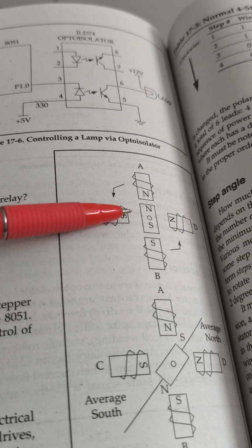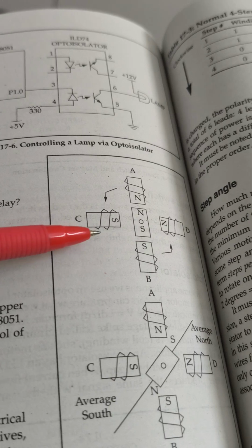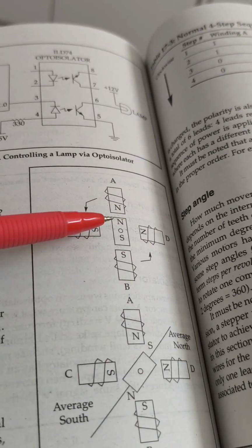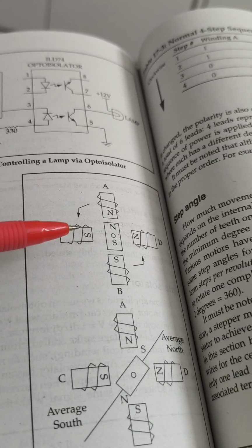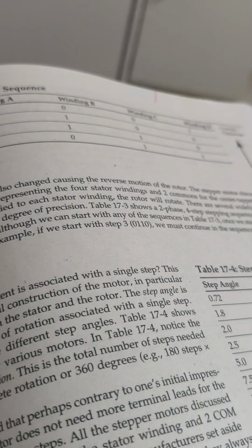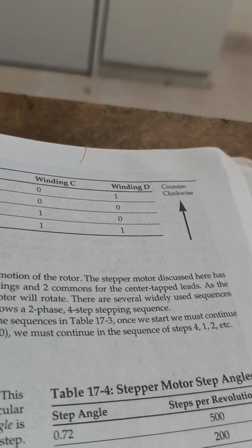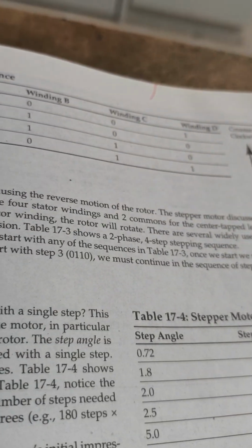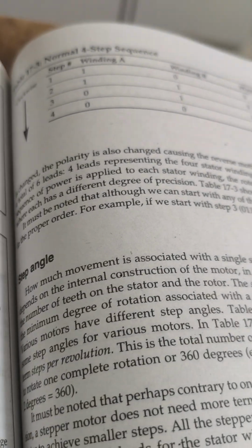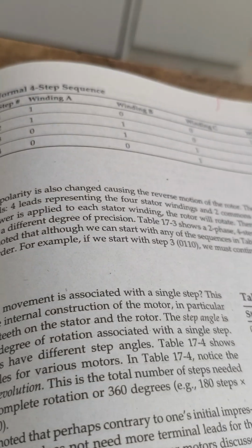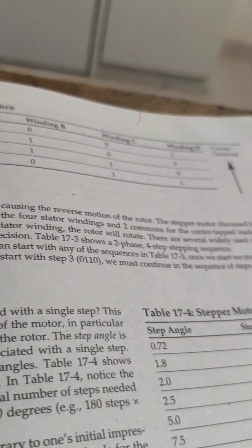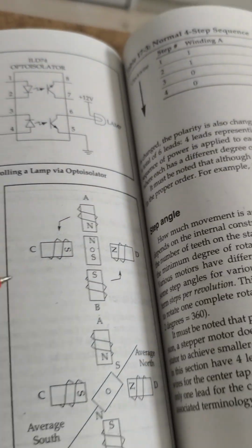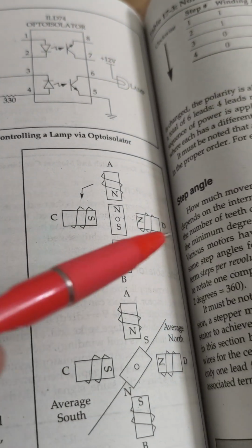Therefore here it is the rotor, this is the stator. Suppose I want to rotate this in the anti-clockwise direction. Counterclockwise means anti-clockwise. At that time, I have to give winding A and winding B 0 0, and winding C and winding D I will give 1 1. When I give winding C and D 1 1,